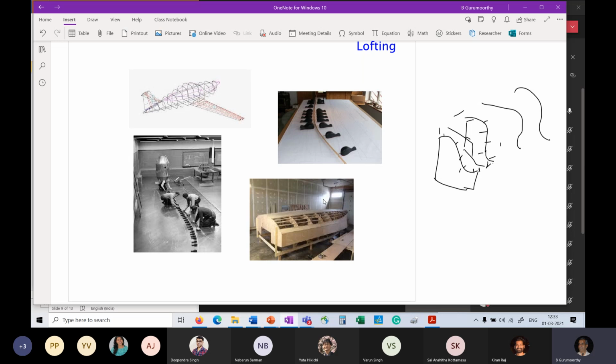So now you have this definition of the shape in the form of these wooden templates. And then your model makers come into the picture. So they'll come into the same room, arrange these wooden templates and fix them on a jig, much the same way you see it in the bottom right here, right? And they will use a softer material like a plaster of Paris or other similar modeling materials, and essentially create the entire object, by filling the gaps between these templates, leveling them with their hand, making it smooth, and then create this shape, right?